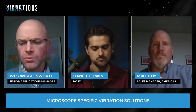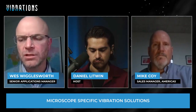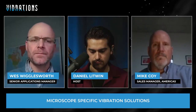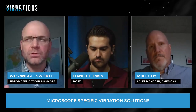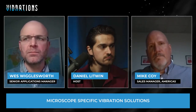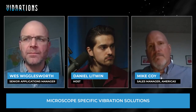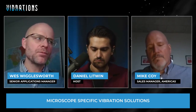And that's why I mentioned earlier, it's really important to think about how you're going to mitigate the current vibration levels, but also think about this phenomenon that the vibration levels do get worse, and that you are considering a solution that even if the vibration levels at the time of install meet spec, because of this issue, you want to really think and consider installing a vibration isolation platform under the microscope at that time, even if you meet spec, because like I said, as the facility is populated and the vibration levels get worse, either